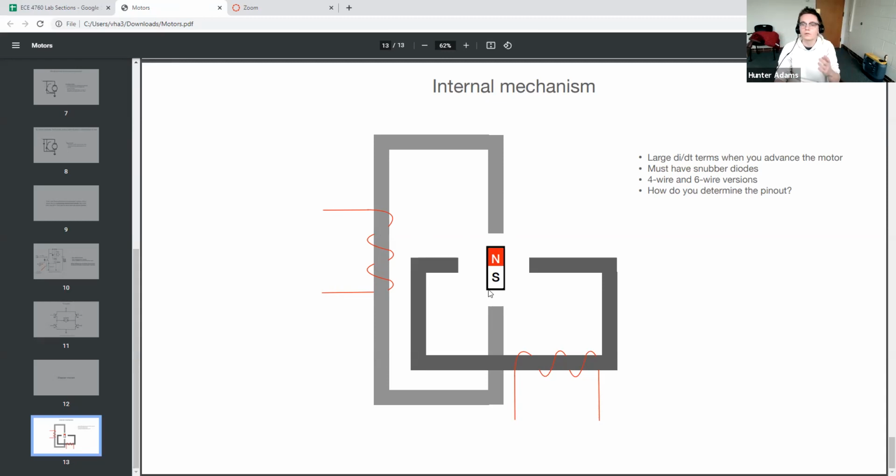And in a stepper motor, depending on the stepper motor, there's a different amount, but generally speaking, there are lots and lots of these stable configurations that you can step through. They're often separated by, I was looking at data sheets this morning, saw a few that were separated by like 1.8 degrees. So you can click 1.8 degrees, click, click, click, click, click.